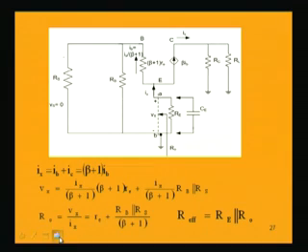So, in order to find that out, we will be finding out the resistance of this left side circuit from this A, B terminals. So, for that we apply an external voltage Vx. This external voltage will be making a current flow in the circuit. One part will go through this, one part will go through this circuit right to the right, and mind it, we have made Vs equal to 0, because the independent source has to be made 0.